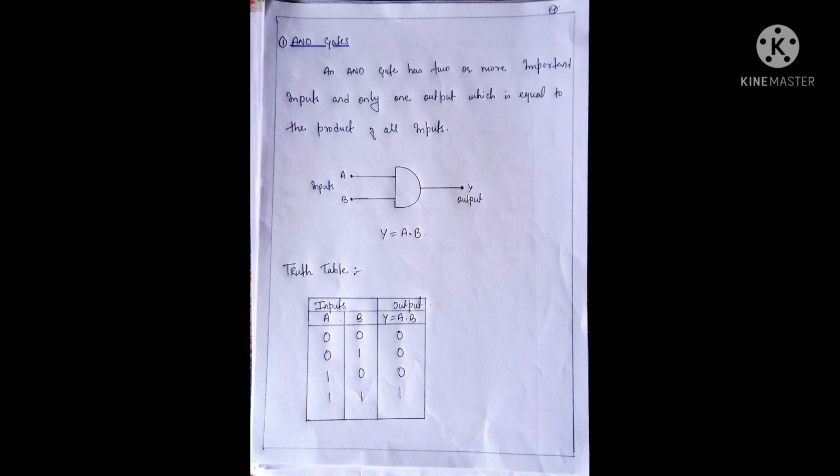The following diagram and table show the circuit symbol and logic combinations for an AND gate. In the symbol, the input terminals are at left and the output terminal is at right. The output is true when both inputs are true, otherwise the output is false. In other words, the output is 1 only when both inputs 1 and 2 are 1.